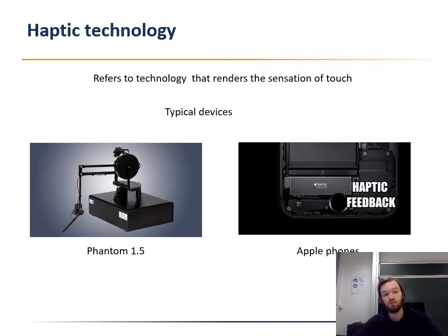So for example, if we track the position of an end effector at any point, we can deliver force. We can think of the scenario where we have a virtual wall here that we're trying to cross, and once we start crossing this virtual wall, we start providing force. Well, how do we provide force? One way is through simulation. And the simplest way is to consider a spring, where force equals minus stiffness multiplied by displacement from the virtual wall. This is again what we use in our lab, but this delivery of force is done through simulation. In our work, we don't want to